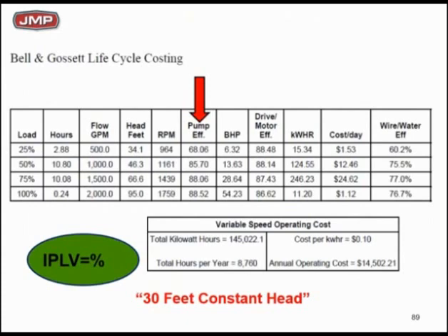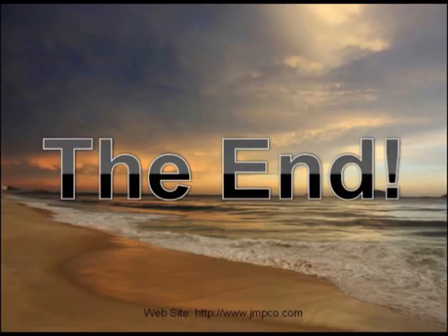Most importantly, what was the electric bill to your client? You promised him $10,000. What is the electric bill? $14,500. Who is going to go to that owner and client and give them a check for $4,500? That's what is upsetting people, and the owners are catching on. We've got to begin to look at the real world. That's why we say to you, let's use some fixed head, don't assume 100% variable, and let's start looking at our load profile like IPLV because it makes a lot of sense.